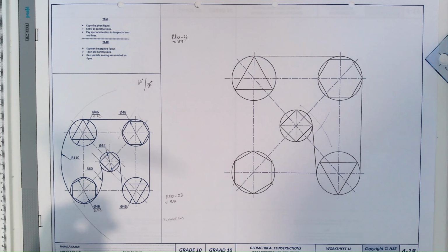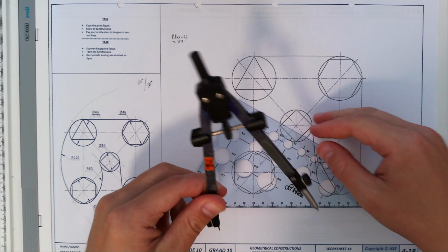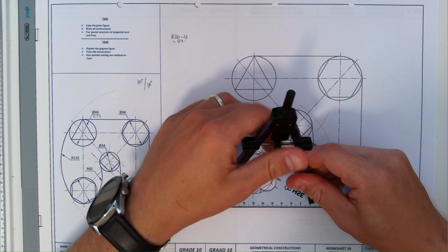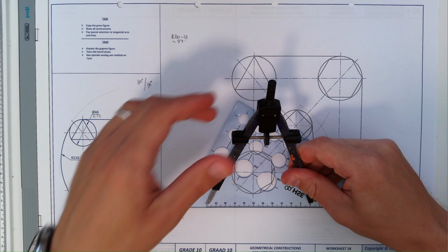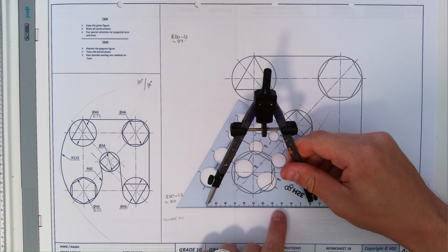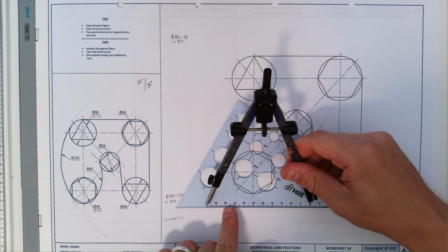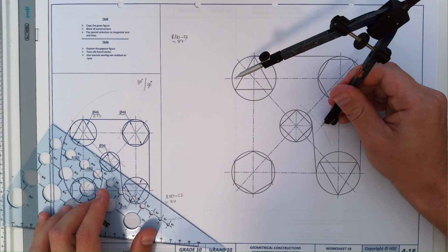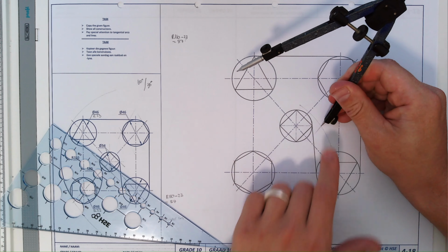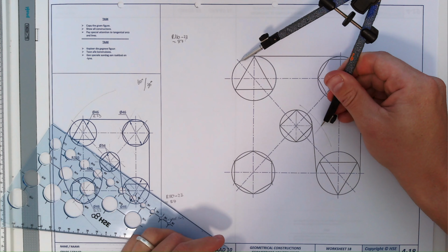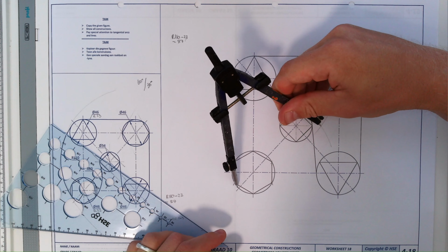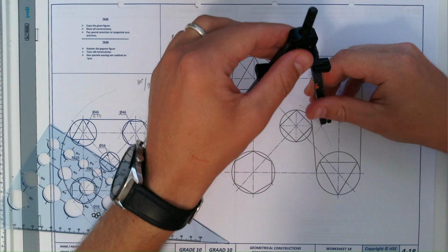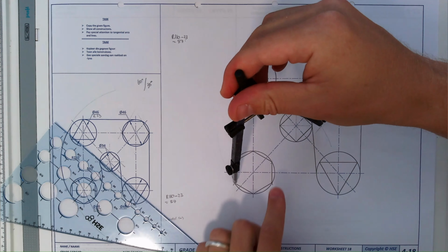The tangent arc has a radius of 110. Now you're going to take your compass and set this on 110 millimeters. So there's mine. 10, 20, 30, 40, 50, 60, 70, 80, 90. Okay, 100, 110. Put your sharp point on that point you've constructed or calculated. And now you notice that arc, look how cool this is. Beautiful. From there all the way to there, we can connect those two circles with an included arc.